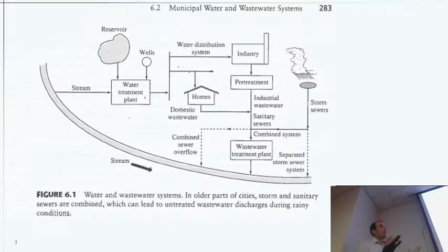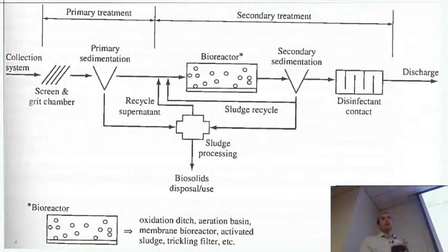At any rate, Detroit would have, and I think they've improved the infrastructure, but they had the capacity to discharge something like 1.4 billion gallons per day of wastewater that went through primary and secondary treatment. But for the cases where they had excessive flooding, and it's fortunately a little bit diluted, so it's cleaner water, kind of, for the extra capacity and the crazy snowmelt season, they could go up to, I think it was 2.2 billion gallons per day, and the remaining extra was only passing through primary treatment. So that's not typical, that's not ideal, but that was, at least for a time, when I learned about it, the situation at their facility.